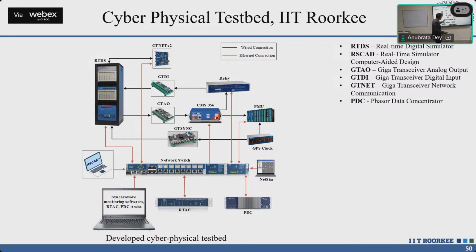So in RSCAD, which runs in RTDS, you can develop, let's say, a 14 bus IEEE 14 bus system model. You develop the system like you would in other software, and then you put the PMU.